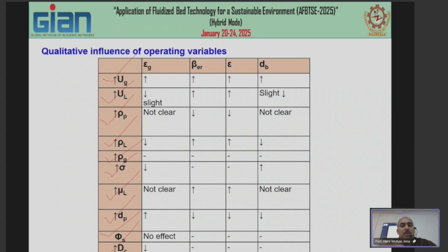So the few parameters of the bed with which the gas liquid solid hydrodynamics is characterized are the gas hold-up, bed expansion ratio, bed porosity, and the bubble diameter.